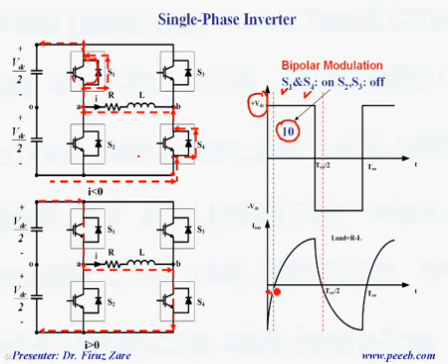And once the current is getting positive, because the direction is changed, the IGBT is turned on, now it can handle the current. So the current passes through the IGBT or switch inside the main switch, and the current is positive. That means this IGBT also can handle the current. So that's why for this period, when the current is positive, current passes through these switches.